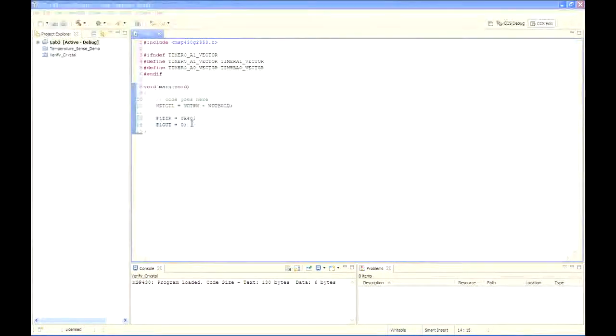In step 6, we're going to go ahead and set up the clock system. Enter a line for spacing and then type the basic clock system control register 3 and then LFXT1S under 2. So that register is one of the basic clock system control registers. In the user's guide, section 5.3, it tells us that the reset state of the register is 5. Check the bit fields of the register and notice that these settings are for a 32 kilohertz crystal on the clock input pins with 6 picofarad capacitors and the oscillator fault condition set.